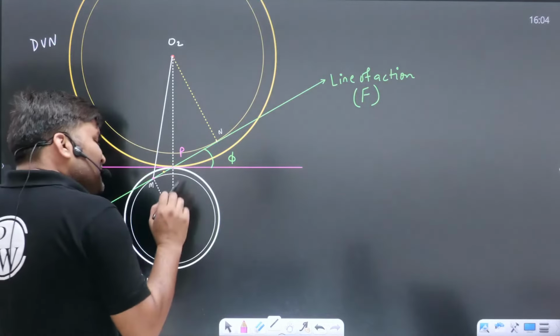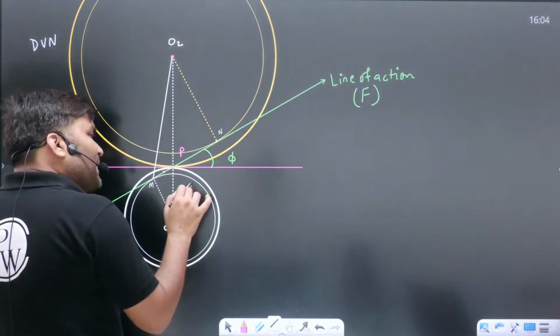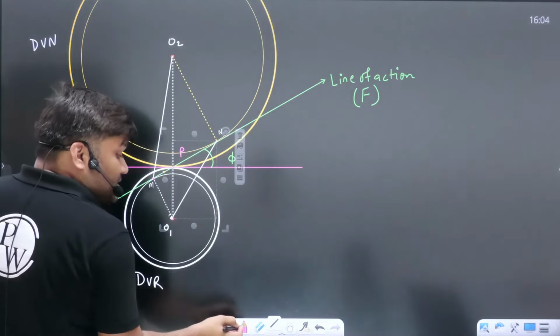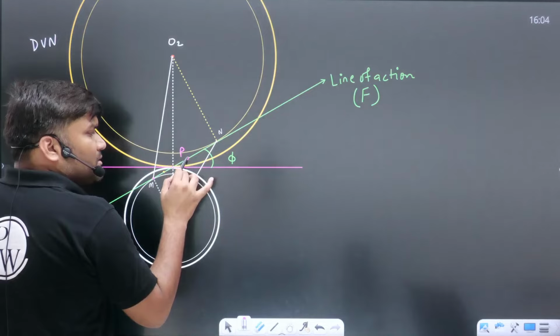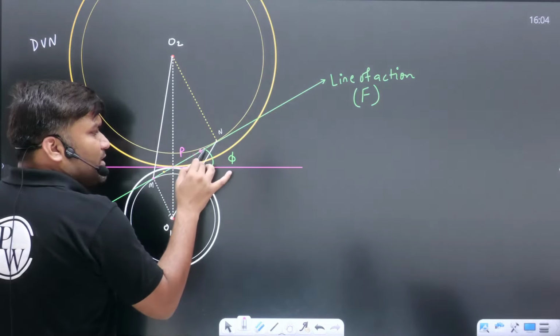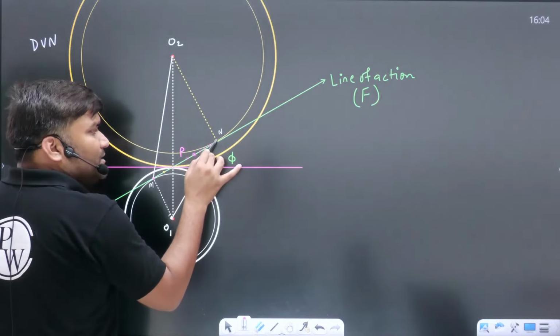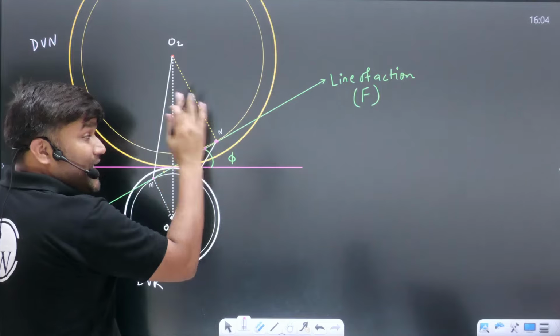Similarly, in the case of the pinion, I will say the pinion tooth can have at most this radius. Beyond that, if the radius of the addendum circle of the pinion is larger than this, can you imagine, beta, the point L, which you are getting somewhere here, as you increase the radius, it will move on this line, and at point N, this is the dead point, beta, dead end.